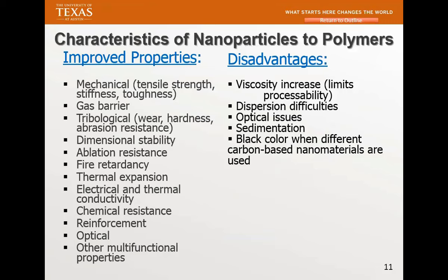The other one I want to caution you about is that some of these nanoparticles, especially ceramic, are very high in density. So when you stir it, it's really good. But when you stop, I'm just giving an example with thermoset, if you don't cross-link it, all these particles are going to sink to the bottom. That's what I call sedimentation. So those are the things you need to watch out for when you disperse your nanoparticle into your polymer.